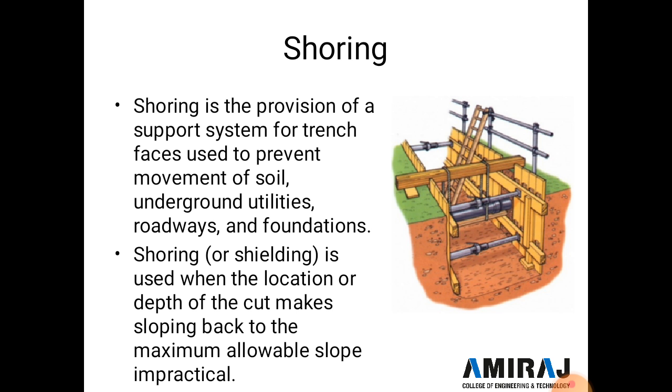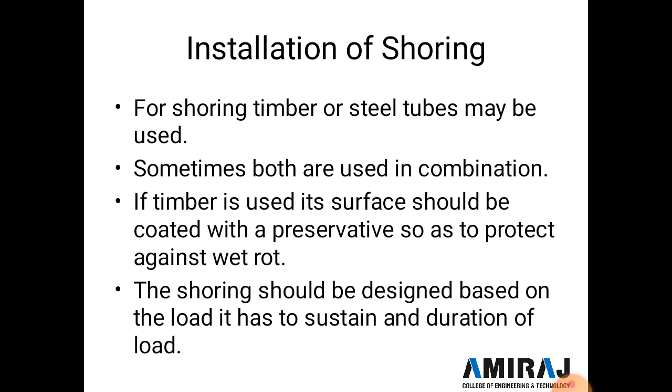Now the next important topic is shoring. In shoring, first we discuss what shoring is. Shoring is the provision of a support system for a trench face, used to prevent the movement of soil, underground utilities, roadway and foundation. Now shoring is used when the location or depth of the cut makes sloping back to the maximum allowable slope impractical. For the installation of shoring, timber or steel tube may be used, and sometimes both are used in combination.